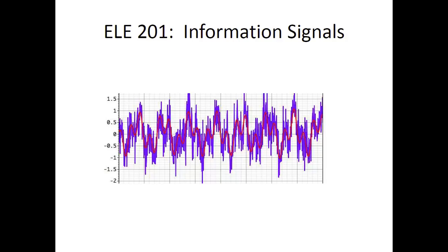Now, you actually can get different effects depending on how you do the averaging. For example, for each output point, you could go a certain number of samples or a certain length of time before that point and after that point and just take an average of your signal. That average then would be your output at that time index. That's one way to do it. But you could also do a weighted average. You could count the points closer in time more heavily and the points further away in time less heavily.